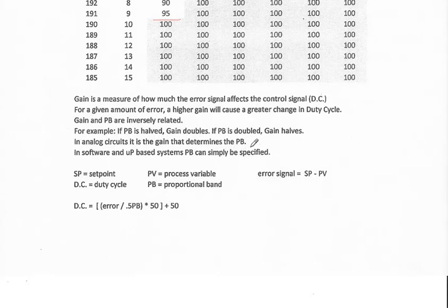When we put this example together in the lab using a PLC, we weren't necessarily thinking in terms of varying a pot to control the gain of an op amp. It was just in the software. So we have our PLC program, and we can simply specify how wide the proportional band is right in the ladder program.